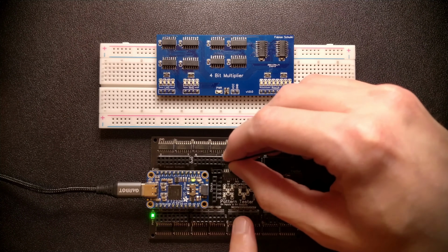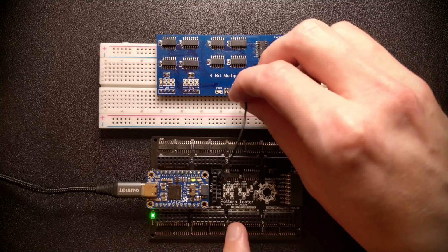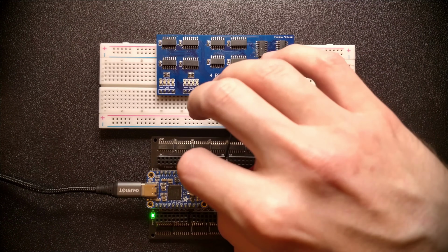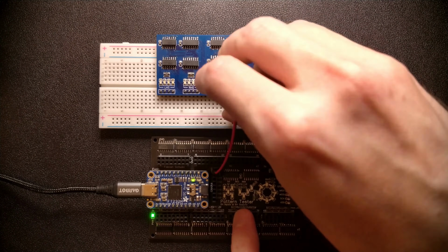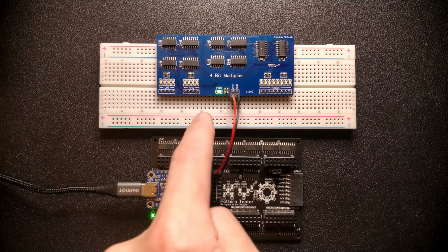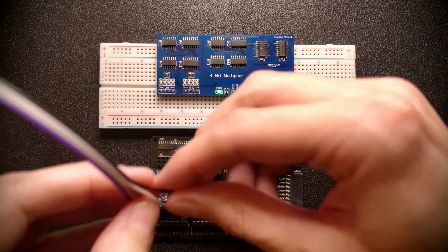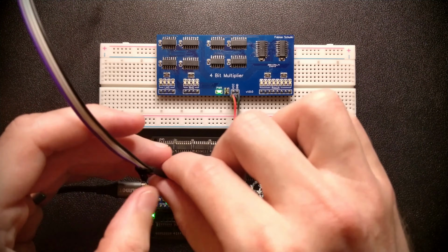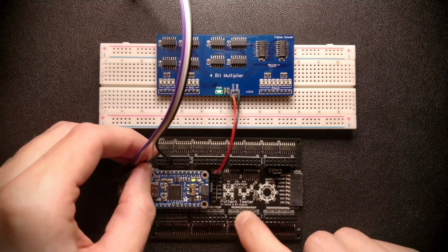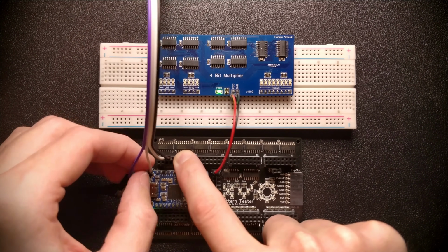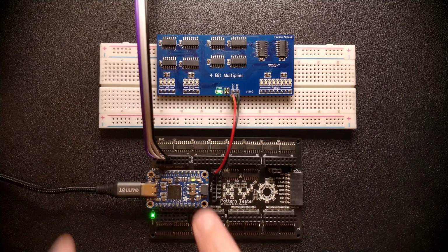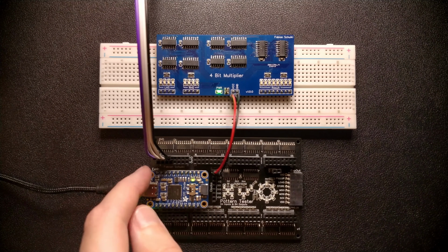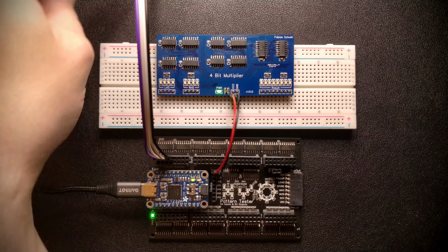So first things first, we need power and ground connections, and we have these handy power headers here on the tester PCB, which we can use. And the multiplier is immediately powered. So let's first start with the inputs of the multiplier. Let's hook these up to the tester board, and then let's see how we can control them from the Python script we're writing. So these are outputs 0 to 3.